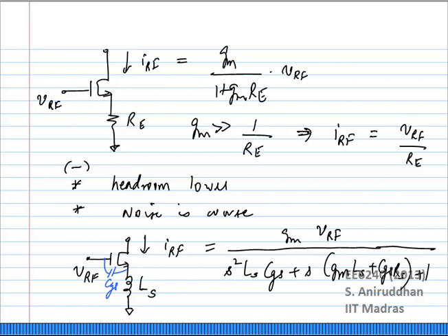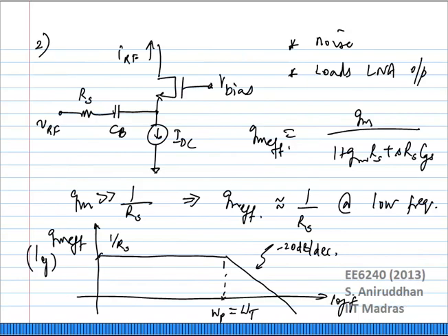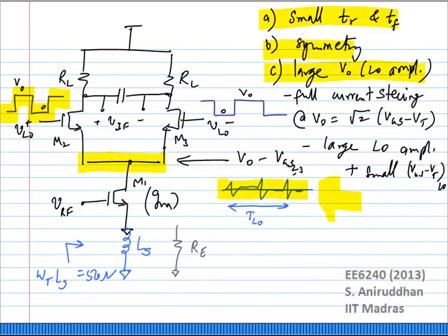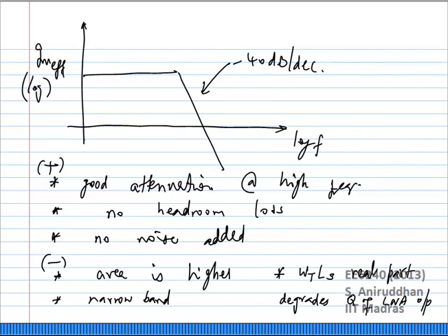Now we wanted to see if this is possible without the use of a resistor. So next we went ahead and said, okay, if you don't use a resistor, what happens if you put an inductance? It turns out you can get some good linearization using the inductor. The problem is you are using up more area, but the good things are it doesn't use a lot of headroom. It doesn't produce much extra noise. And the other thing is it actually produces a second order system along with the CGS of the transistor.